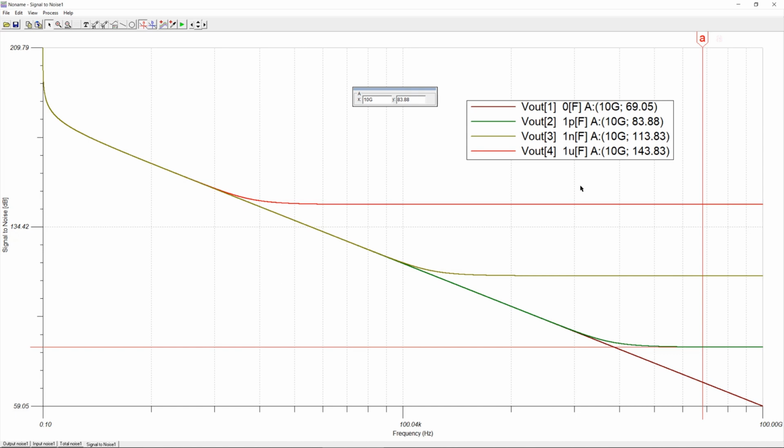But now we have also seen how to generate these plots in SPICE, which is of course a little bit helpful when you need to do that by yourself. Okay, this was our example about another RC circuit where you see two resistors, so you have a voltage divider action with a capacitor at the output for filtering action. Of course, the calculations are not that difficult if you do that step by step in a straightforward manner. But what is really important is where you look at it, and if you look at the input, you don't consider the filtering. So that's one of the important messages from this example.